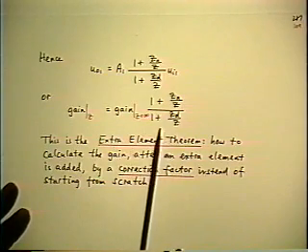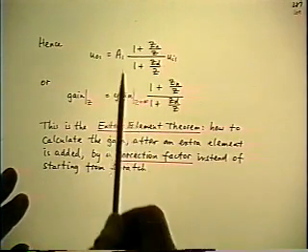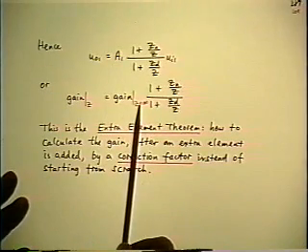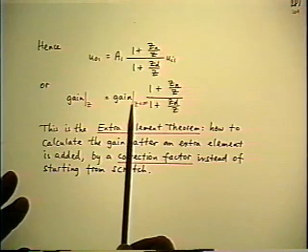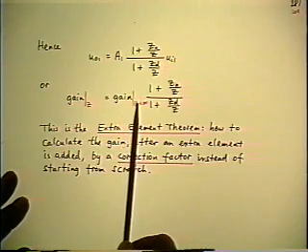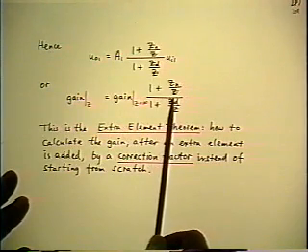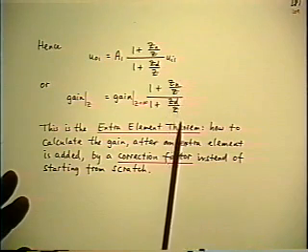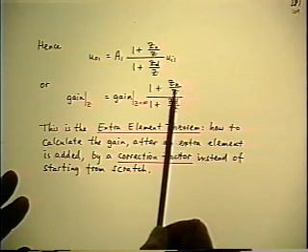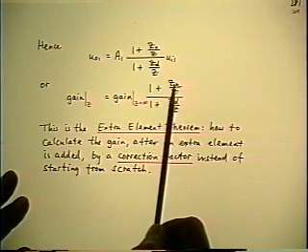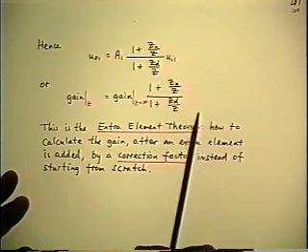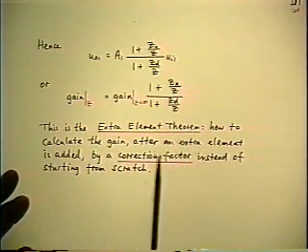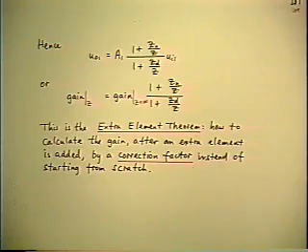In other words, we've derived what the objective was. If you've already calculated the gain of the system, and you decide later on you want to put a certain element Z in addition, all you have to do is multiply the answer you already got by a correction factor that involves the extra element itself, the Z, and 2 parameters, Zd and Zn, which are the driving point impedances of the original box at the place where you are going to add the extra element.